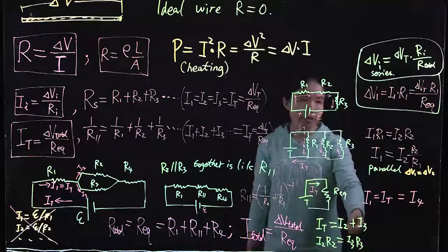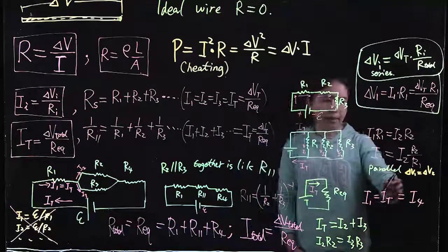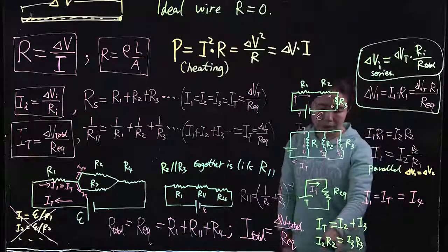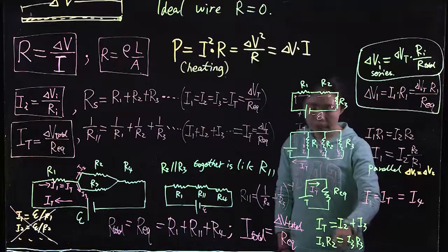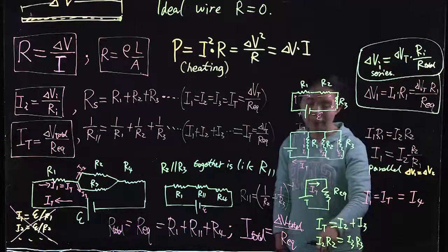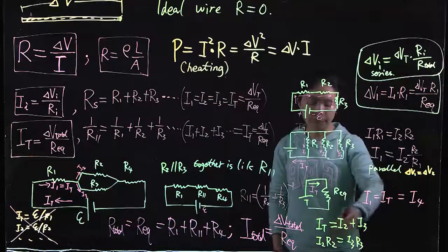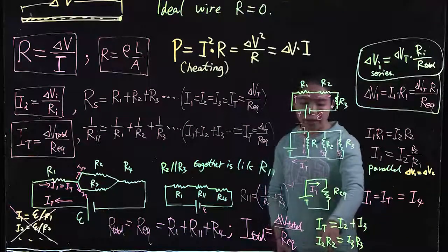Using these two equations, we will be able to solve I2, I3 separately. Notice that if you divide one of the R to the bottom, if you have a large R, you have a small current. If you have a small R at the bottom, you're going to have a larger current. And then you can substitute this back to this equation, solve for each one of them. Okay? And then you know each individual I1 and I2.